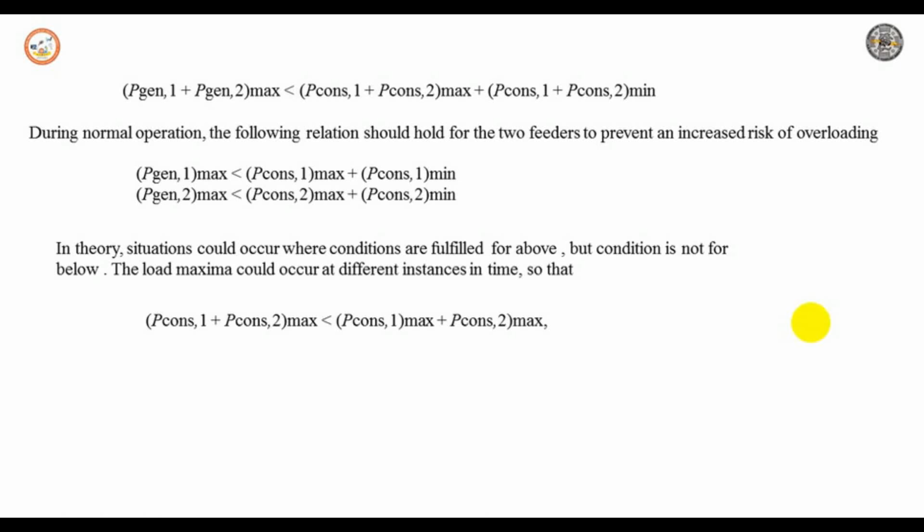More advanced solutions could be considered where hosting capacity is calculated after every switching action. The production from distributed generation is curtailed once it exceeds the hosting capacity for the actual operating state of the distribution system. In either case, there will be no limit on installed capacity, only on the actual production of power.